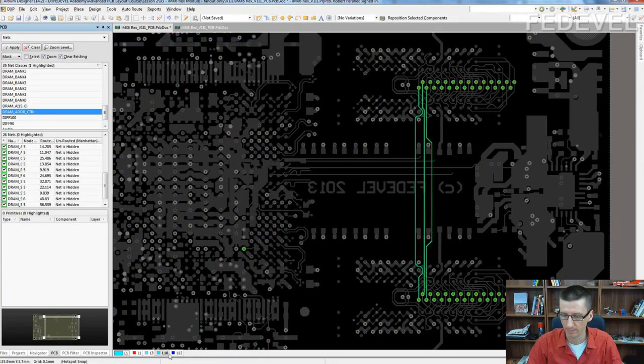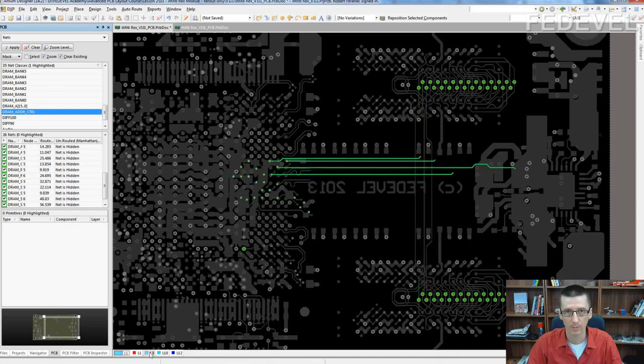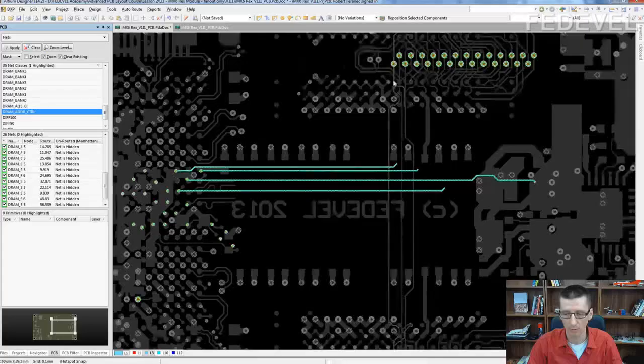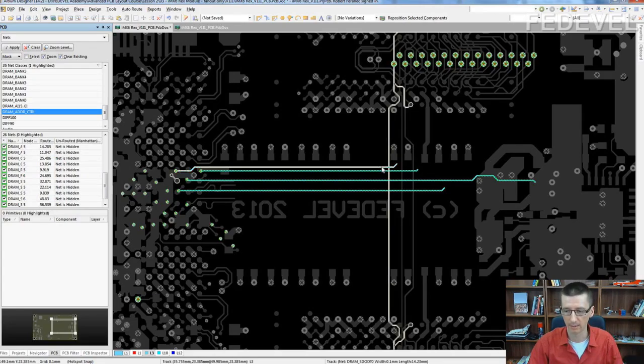And place the vias. Again, always when I'm crossing tracks, when I'm changing layers, I don't draw the full connection because it's much easier to place the vias later. You will just find the track.